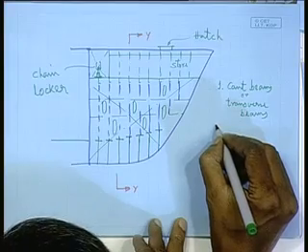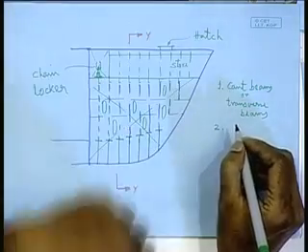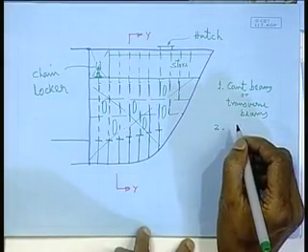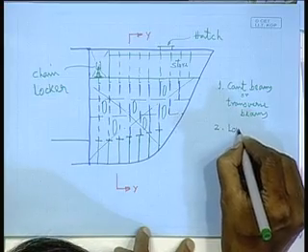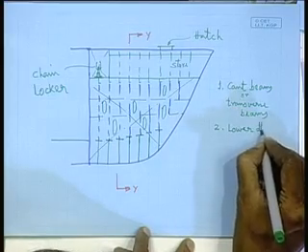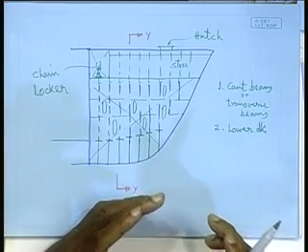Then second, what are we doing? By providing another lower deck, that adds to the strength. The lower deck also provides some strength. It's worthwhile to provide a lower deck, because then I carve out some space for carriage of some items, not cargo.